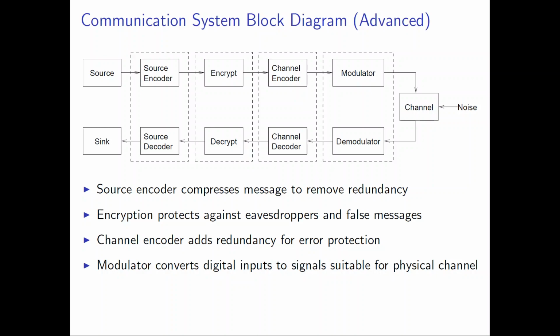It is lambda over 4. 32 divided by 4, 8 centimeters. 8 centimeters, you can put them in your phone. But if you use 100, the wavelength will be 3 meters. 3 meters over 4, still you have 75 centimeters. 75 centimeters, you cannot put them in your phone. We gave this example last time.